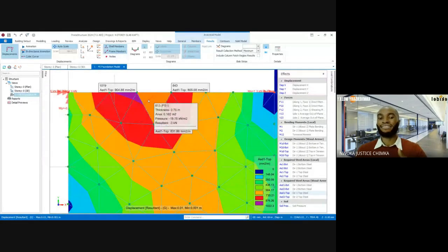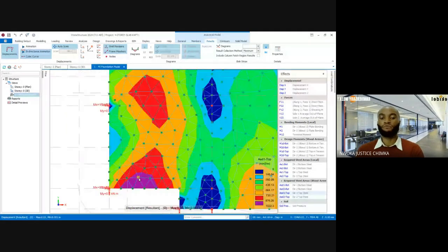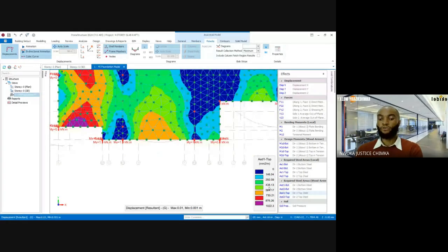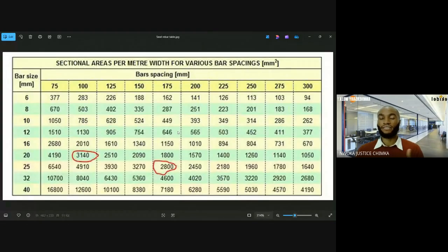And even if we had that slab extended at least 300 or 500, but 300 is the minimum, that's what I use, you'd have seen that this purple wouldn't have appeared. So even if we have to take this purple, which is 1022 as our general area of steel, it will still fall within diameter 16. 1022, so we can take it to 1025, the round figure.